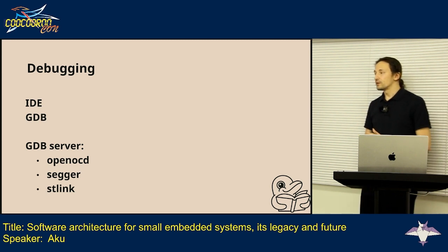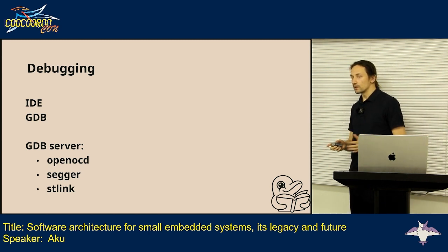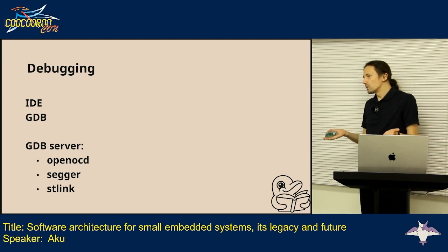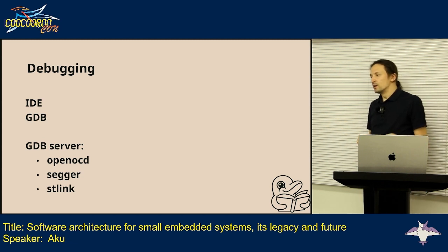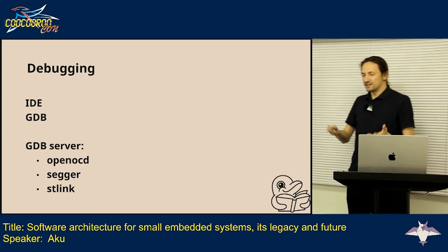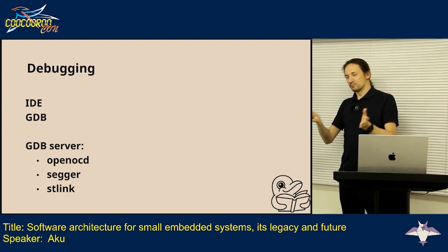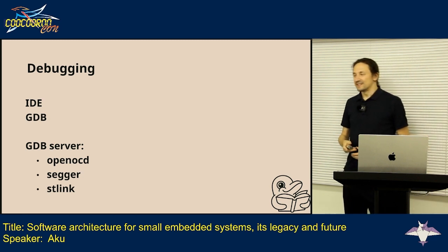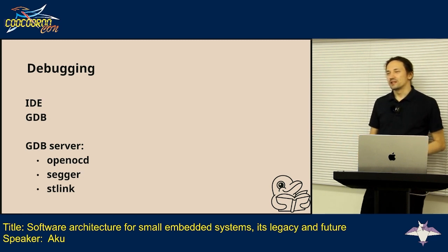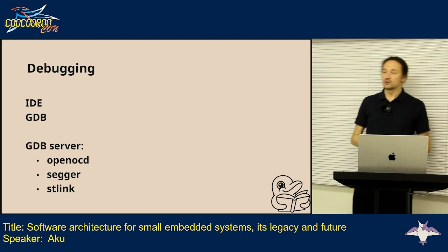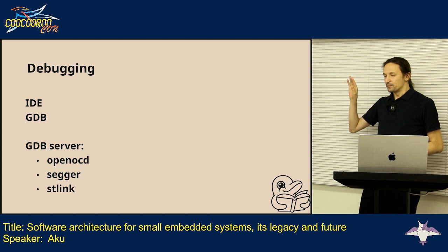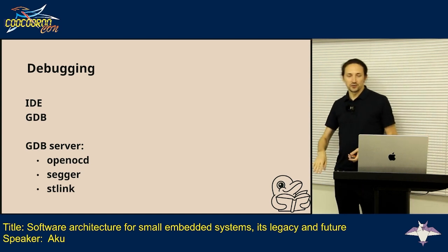Obviously, some architectures are not debuggable. Like they just don't have a debug port, like at all. Like all 8051, they just don't. You either made a mistake and it just stopped, or broke your system, or maybe burned itself, or it works. So those systems we usually debug with printfs, or the simplest way to debug is just to control the pin itself. You just set it to high or to low.